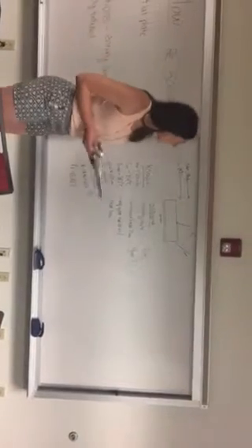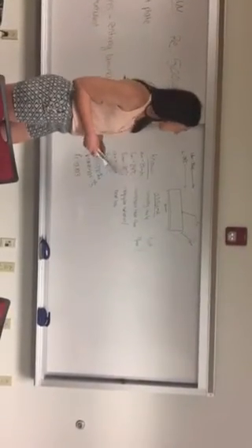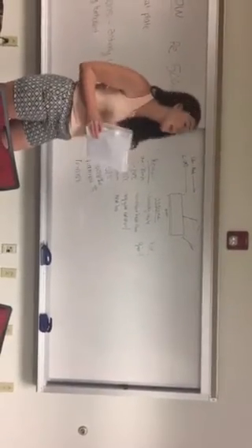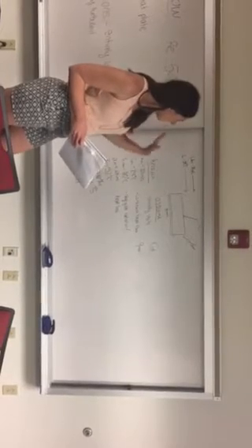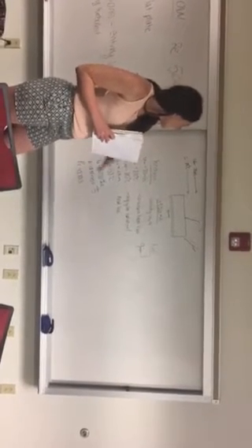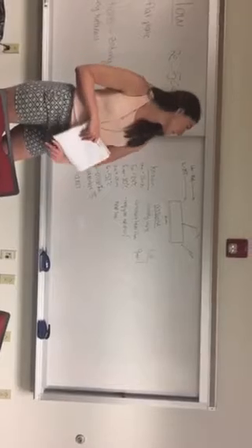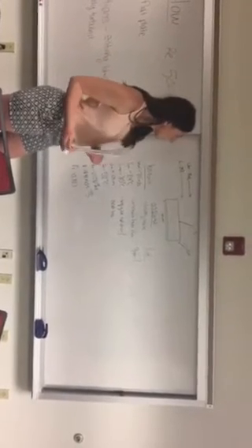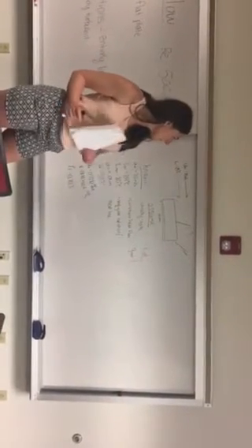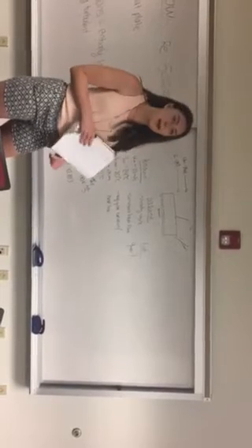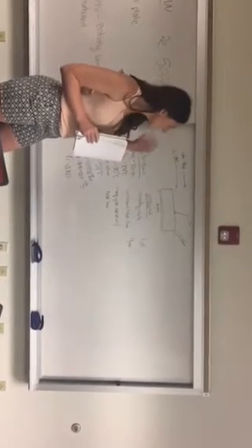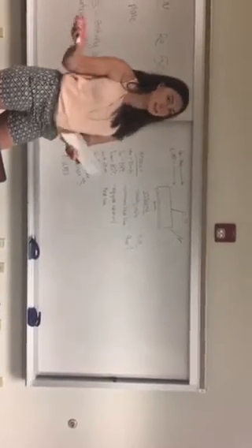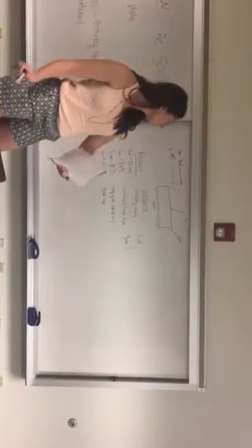In this problem, we have a silicone chip, and it is being cooled by having air blow over it at 20 meters per second. The air is at a temperature of 24 degrees Celsius, and your chip is 10 millimeters by 10 millimeters. We are going to find the maximum power or heat rate that can be given so that the chip does not exceed a temperature of 80 degrees Celsius.